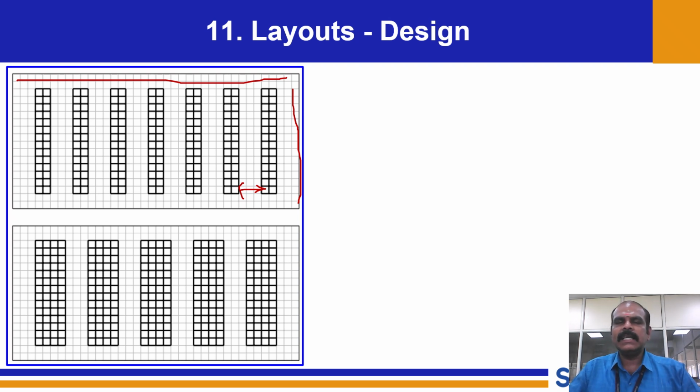So this is single layout, where you have access only on either side. In between you will not be able to access. So this is how it goes on. When you think of the second, you can also cluster, but this clustering of racks will be based on the product width. The product will be deciding. However, we should try to stick to the minimum aisle requirement, because half the width of the product will be accessed through this aisle. So this has to be considered.